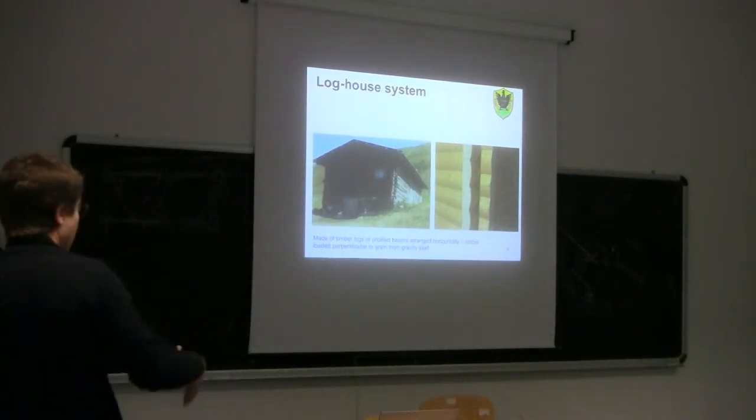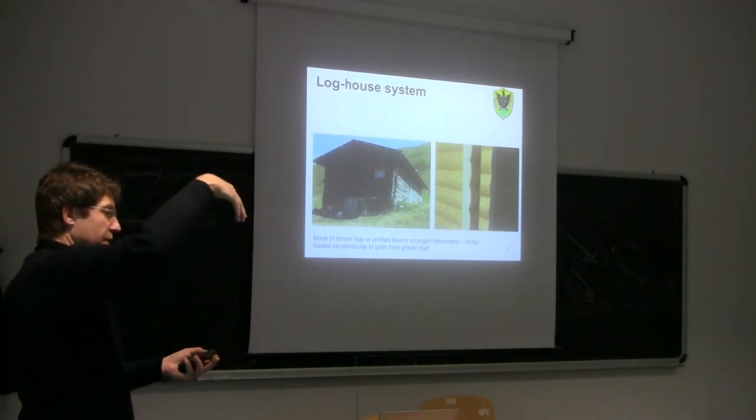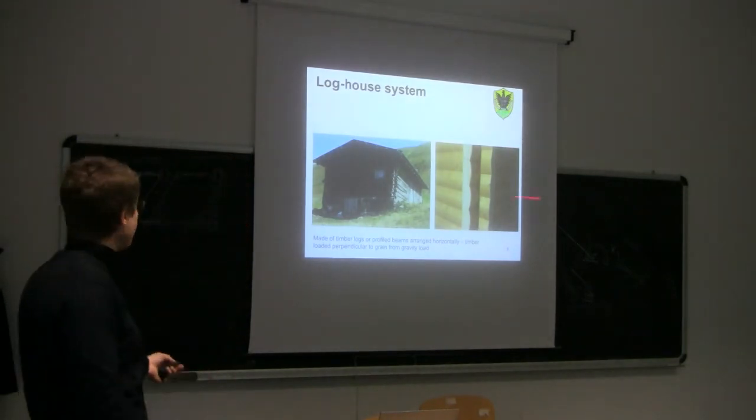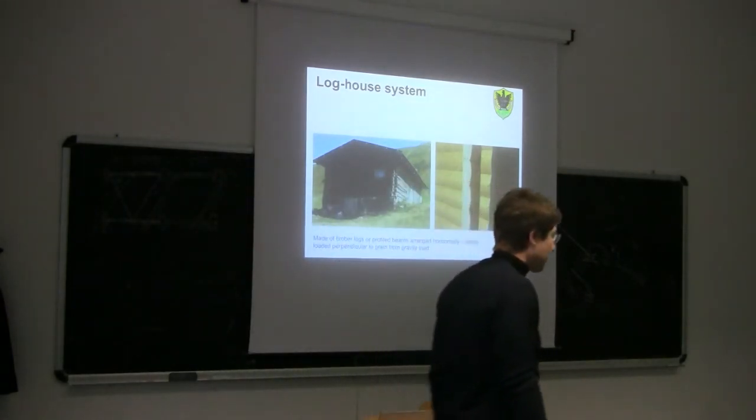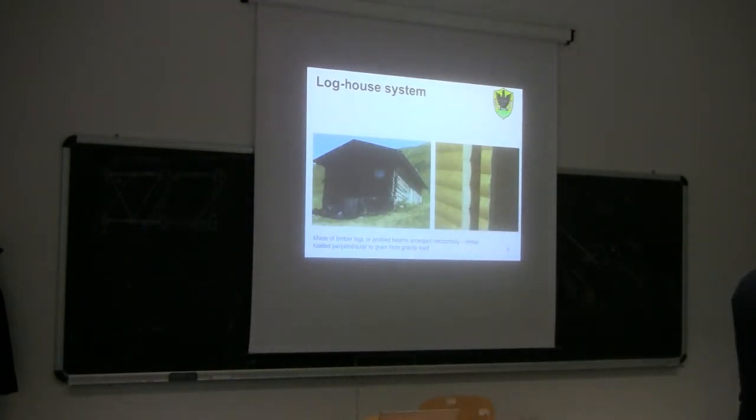So all the vertical loads are inducing stresses perpendicular to the grain into the logs, which may seem strange because if you remember, wood does not perform very well perpendicular to the grain. However, we also said that perpendicular to the grain, compression is not so bad. Tension is very bad, but compression is not so bad.